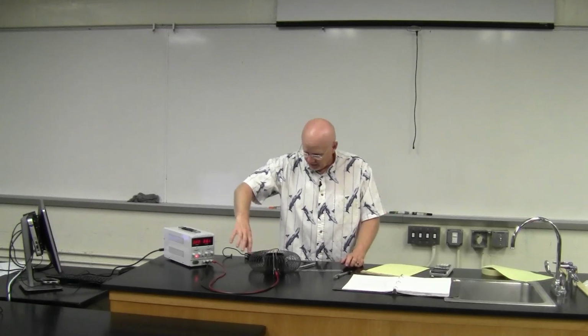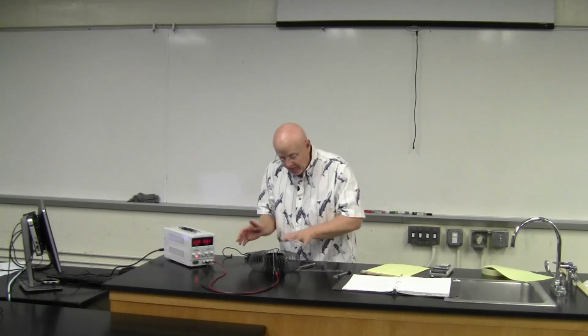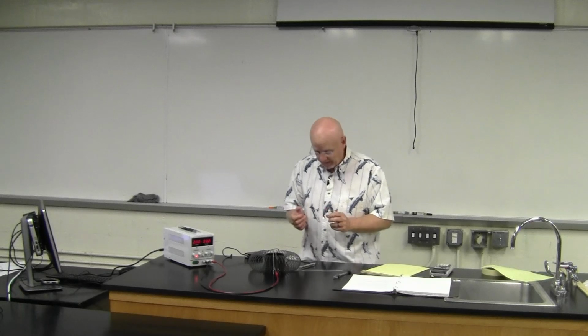If I can even turn it on, I was playing with it and I adjusted it to 2 amps, and that's what the procedures say. They say set up the toroid, and again, set it for 2 amps, because if we go to the 2.5 like we've been doing, remember the toroid tends to be stronger than the solenoid, and we go beyond the capabilities of our magnetic probe, so we don't want to go anything above 0.4. Even 0.38 is really pushing our probe the way it's been calibrated and set up. So I didn't want to do that, and that's why the current is set up.